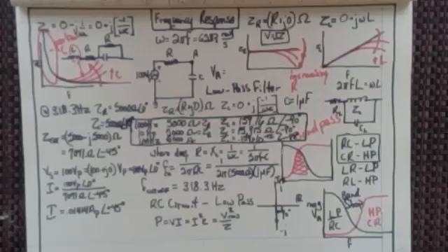And that's another way that you can always check. If you're working on an oscilloscope and you want to find out what your resonant frequency is, and you don't really know what the resistance and the capacitance and whatever is in that RC circuit that you've got, you could easily figure that out, because you just dial it in until you see that current compared to the voltage is going to be at a 45-degree phase shift.